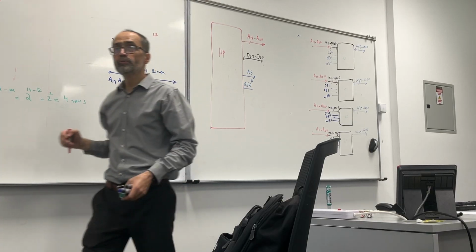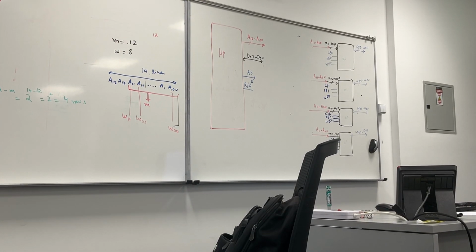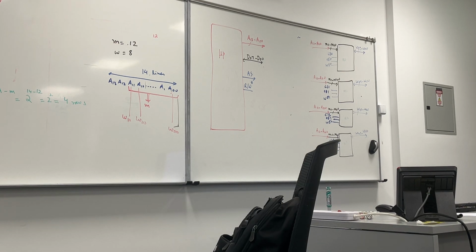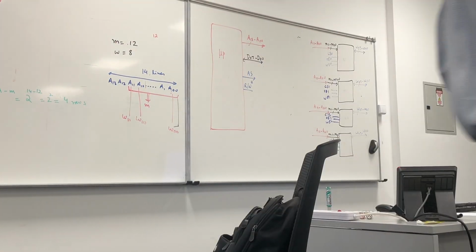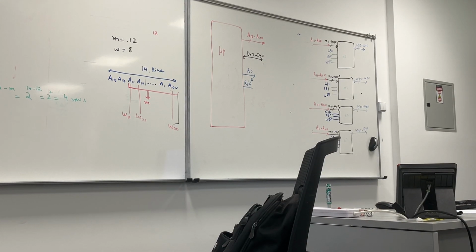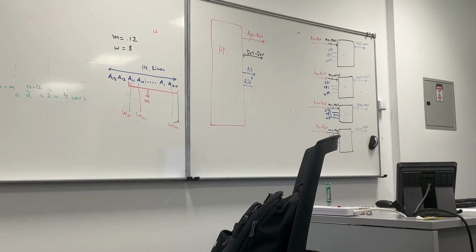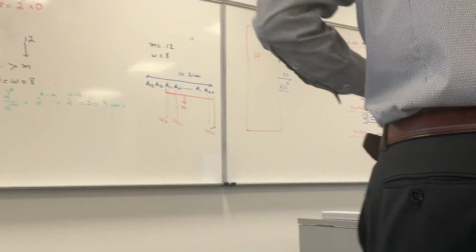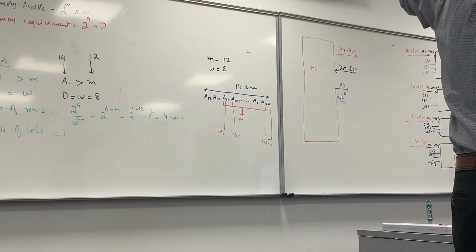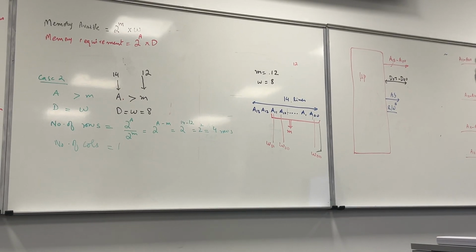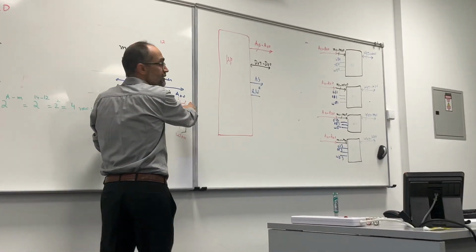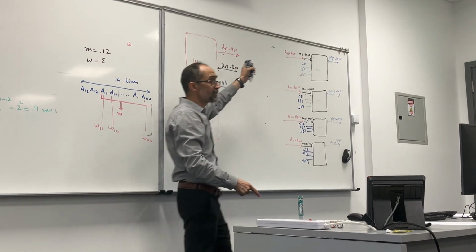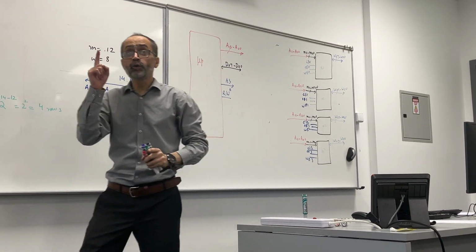What about the remaining 2 bits? Mux? No. What about the remaining 2 bits? Anyone? No. Please remember, there are 4 memories, and I will explain one more important thing that will be paired with a question of your midterm. The problem is that we have 4 main memories: memory 0, memory 1, memory 2, and memory 3. The lower bits of the address lines of the microprocessor are connected to the address lines on the main memory side.